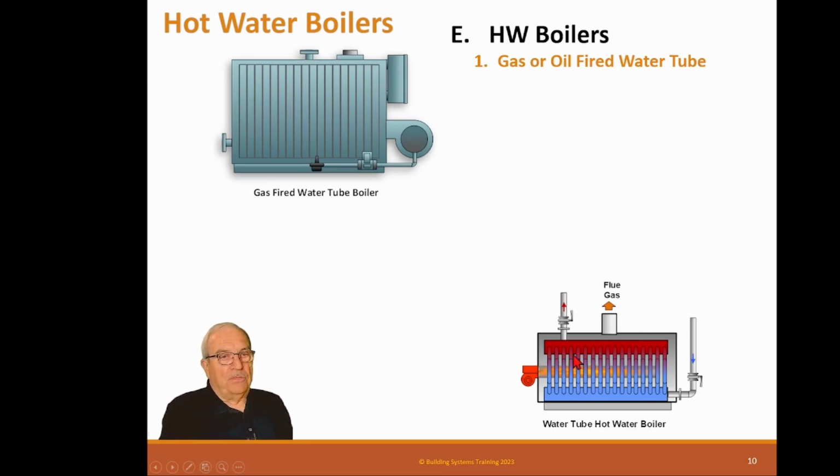The only problem with these boilers is that this water temperature here must leave the boiler at a certain temperature to prevent condensation on the boiler tubes. So normally it's something like 130 to 138 degrees. So when you set these boilers up, they must never allow that colder water to leave the boiler, because it'll condense, and that'll rust these tubes and it'll destroy the boiler. I've seen brand new boilers be destroyed within 3 months because they didn't have them set. They were doing 120 degree water or something that's cold, and that should not take place.